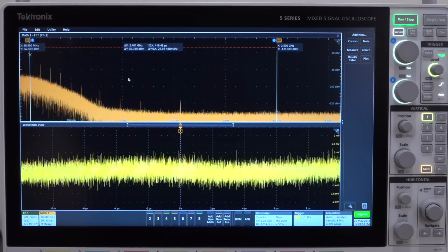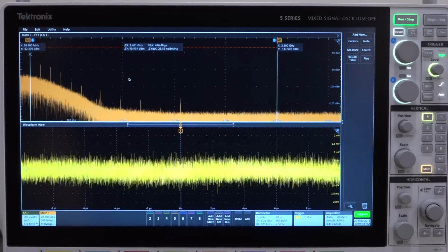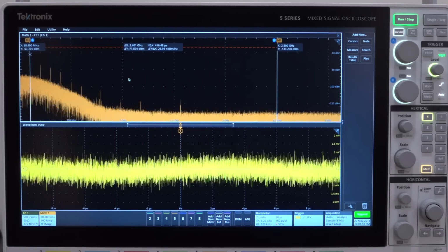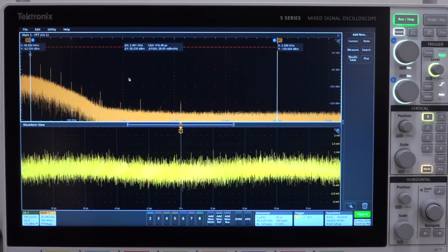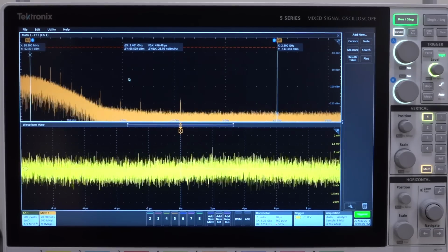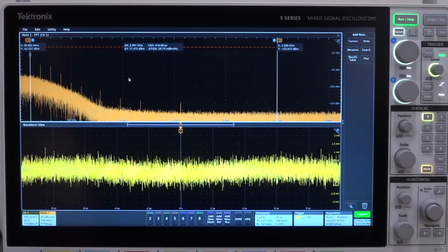So there is a little bit of limitation from that point of view, but still the fact that we can get such small fine steps at such high frequencies as 100 megahertz in order to be able to create this type of signal is impressive. Remember, this doesn't have an attenuator in a traditional sense. So this is all done with amplifiers or from the output of the DAC with built-in variable gain amplifiers that are there. So I'm fairly happy with this.